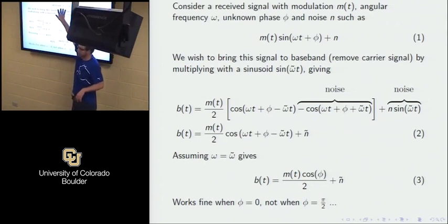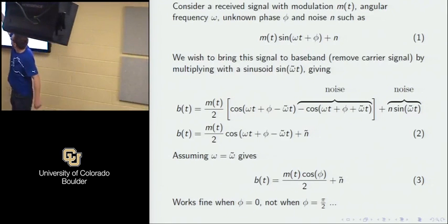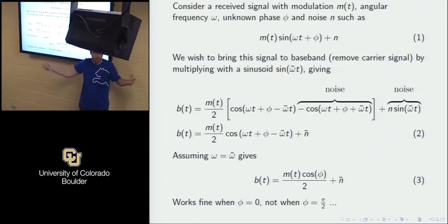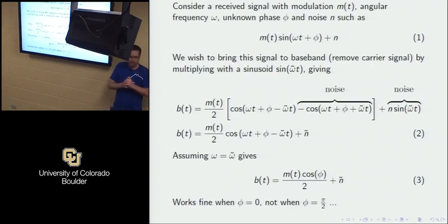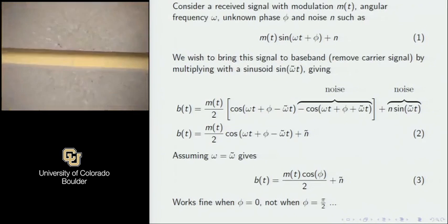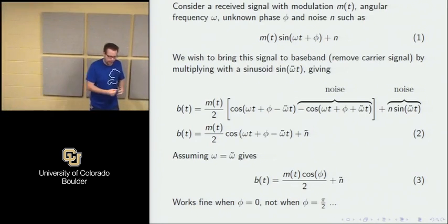And we multiply this with a sinusoid, right? This is a signal that we have: a code, for example m of t, with the carrier frequency sinusoid multiplied with that signal, whatever it is. Does it make sense? And we have some noise. Then we want to bring it down to baseband. I've shown you the examples of what happens when you correlate. That is only valid at baseband, so we need to have a very low frequency of the carrier of that signal.